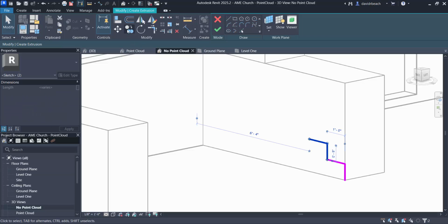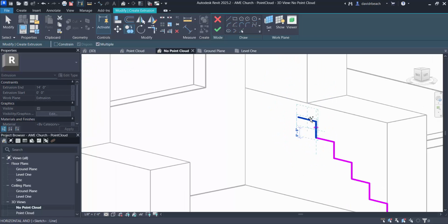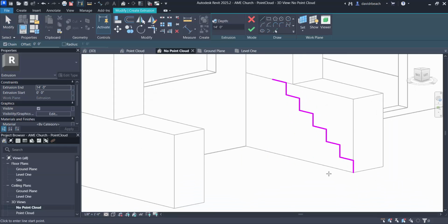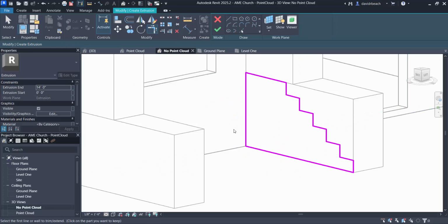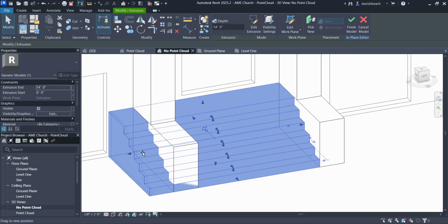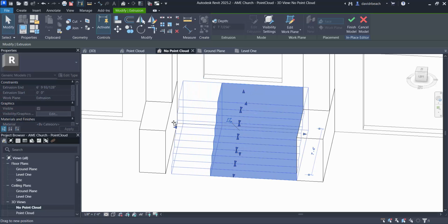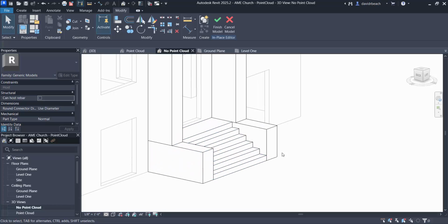and I can keep drafting that angle out, or I can also just select and copy to build the stair like that. And then I'm going to close this off, and I'm going to trim those last 2 pieces together. Then I just need to extend those 2 things out. I'm just going to use the grip and lock that to the inside edge. So that's how that porch shapes out.